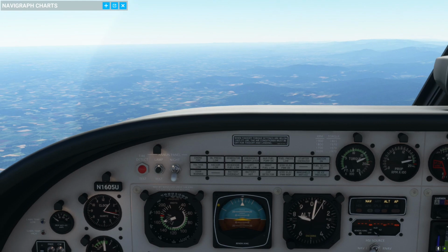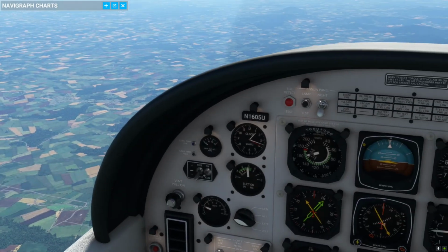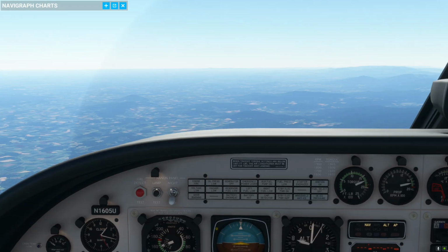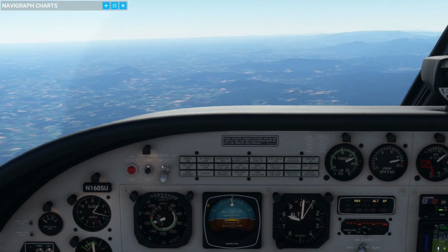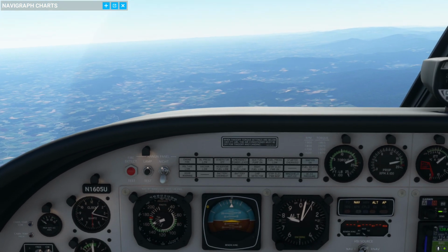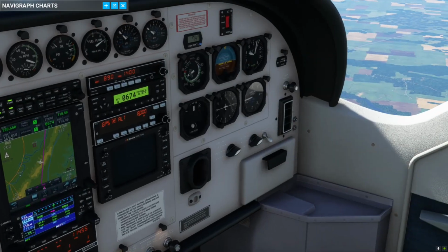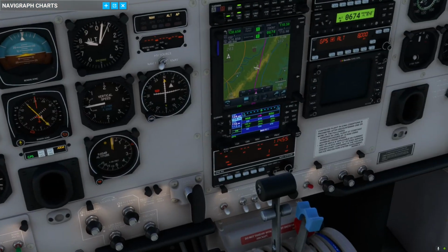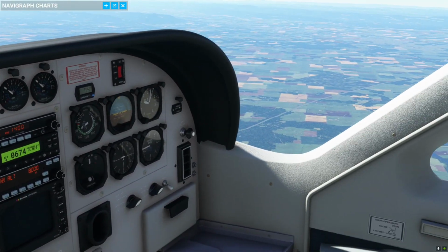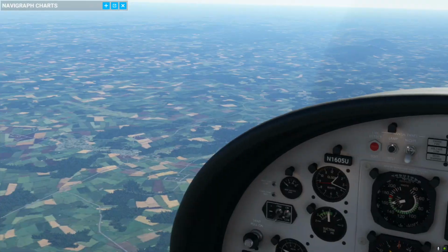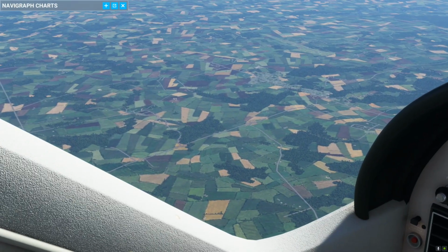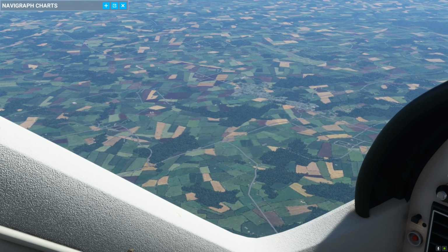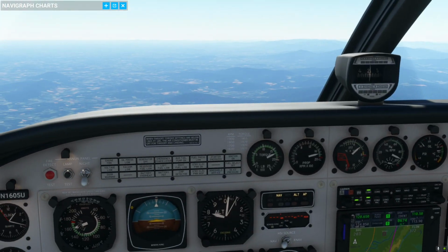And my notes say best glide is 105 in this 208. We lose an engine, we trim for 105, look for a place. Once we find a place, then we run checks to see if we can get the engine restarted, figure out if we have a fuel problem, something else. And if we can't get it restarted, then we just continue with the plan and put her in the field. Or on a highway. Here I would probably choose a field. The 208 does not need a ton of runway.